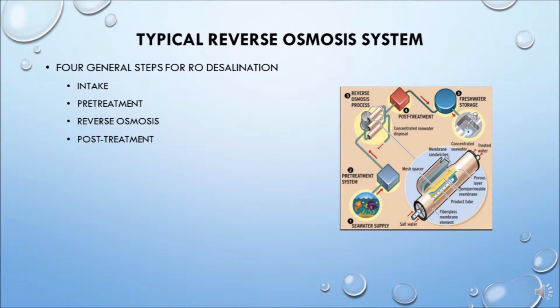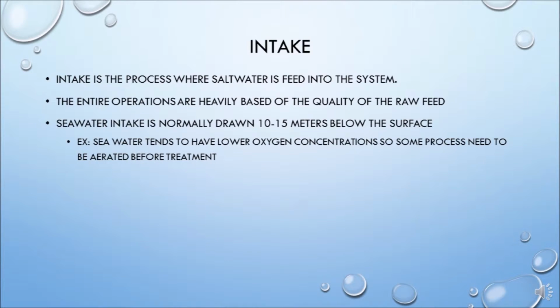The typical reverse osmosis system. There are 4 general steps for the reverse osmosis desalination: intake, pretreatment, reverse osmosis, and post-treatment. Intake is the process in which salt water is fed into the system from a water source.